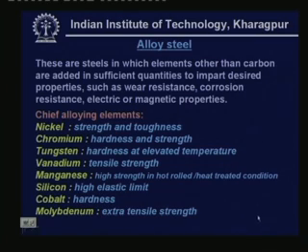Vanadium increases the tensile strength. Manganese gives high strength in hot rolled and heat treated conditions. Silicon imparts high elastic limit. A high elastic limit is a desirable property, because the deformations in the machine elements will then stay within the elastic limit even for a higher load.